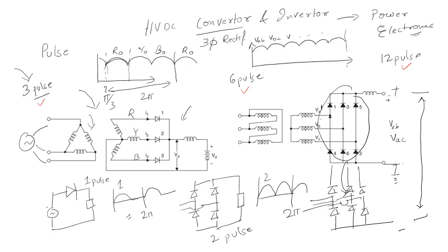More like a DC supply means your DC supply is actually a straight line. Now if you see here, for a single pulse converter, if you draw the straight line, it has a gap here. Okay. Similarly, for a two pulse supply, the number of pulses is very less, so it resembles less like a DC supply.